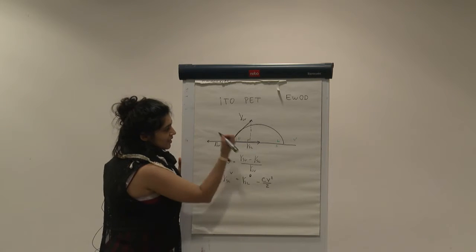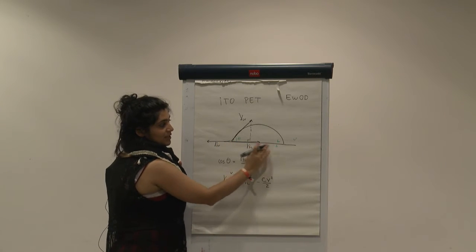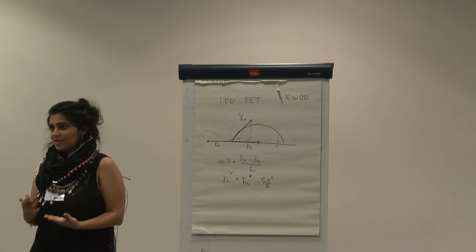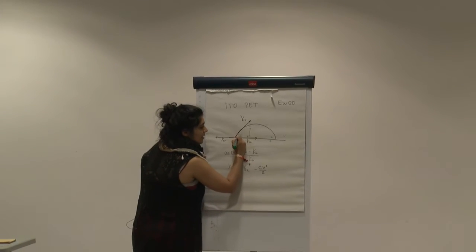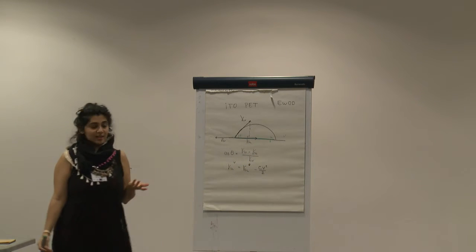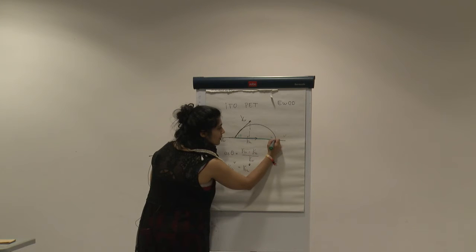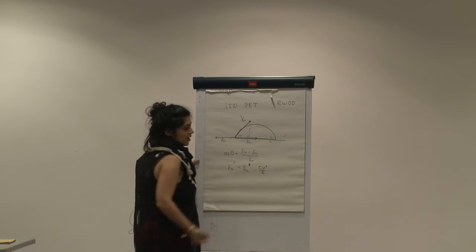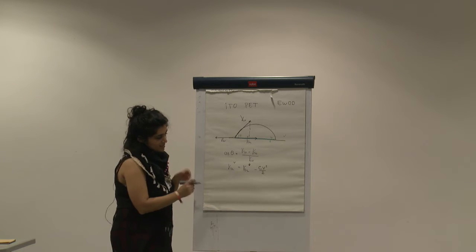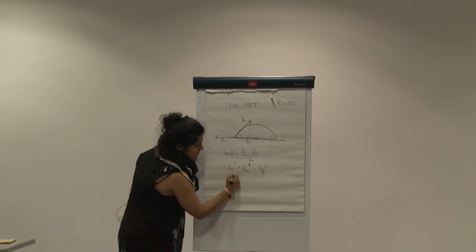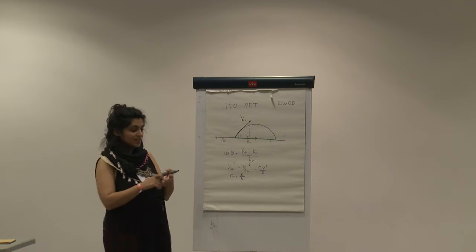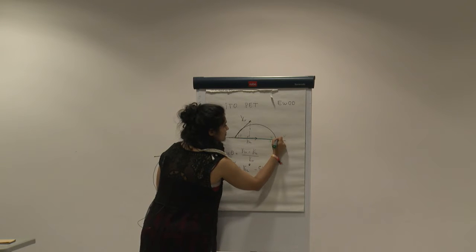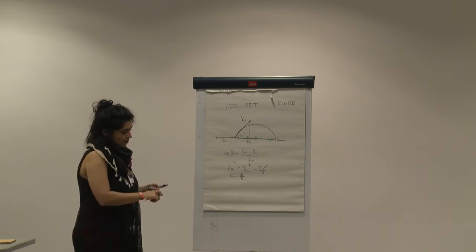And now what happens is that in between the electrode and the droplet, there is an insulator layer, right? You cannot have the droplet directly on the electrode, otherwise you have sparks. So at this insulating layer, the layer is dielectric. The way that the ions arrange is described in this capacitance, and the capacitance value is the dielectric constant over T. In this case, T is the thickness of the layer.